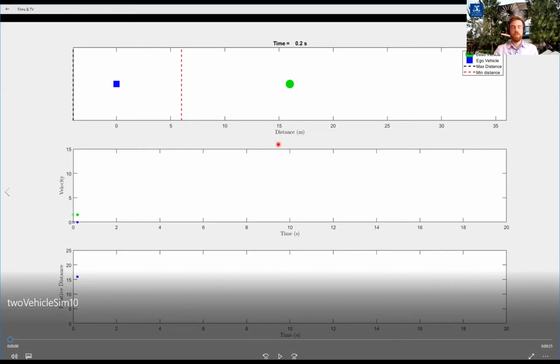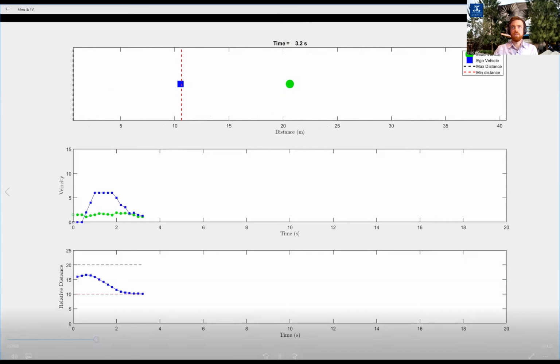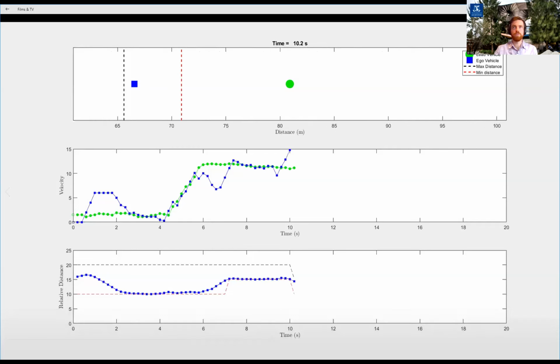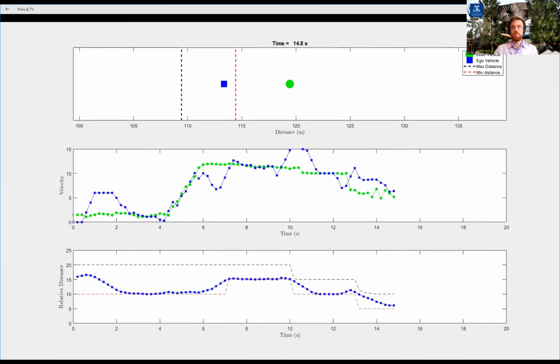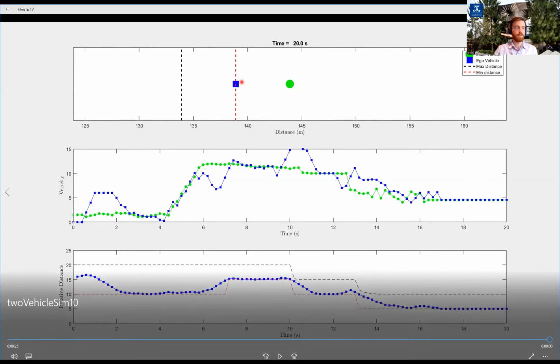And we'll also see, say, around the 13 to 16 second mark, that the ego vehicle will back away from the constraint as well, because that's that period where there's larger uncertainty in the velocity of the lead vehicle. So you can see when there's little uncertainty, it tracks pretty closely to the constraint, and then just before the constraint changed, it backed off. And here there's a bit of large uncertainty, so it backs off, and then at the very end, there's almost no uncertainty, so it's almost tracking right on that constraint limit.